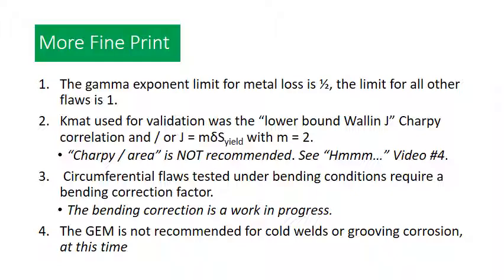I've done some validation to circumferential flaws, which have been tested under bending conditions, and I've developed a bending correction factor. You can see that in video number 4. That's a work in progress. And I'll say right now that the GEM is not recommended for cold welds or grooving corrosion. It's a little tricky to find consistent data on that matter. I do have some cold weld data, but unfortunately there don't seem to be any toughnesses available for the actual bond line, and that makes the predictions quite difficult.